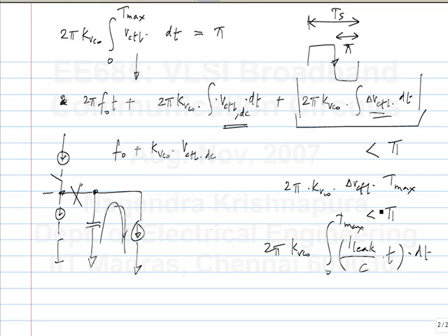In any other case of any other error, you do the same thing. If you have a time varying delta V control, you want to calculate the amount of phase deviations, that is the phase jitter, and you again use the same formula. The ideal phase of the oscillator is 2 pi times the frequency of the oscillator times time. Whatever is in excess of it is the phase jitter or phase error, which you calculate by putting the appropriate value in the control voltage.